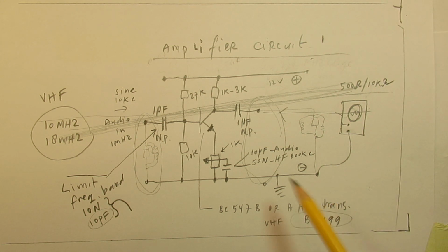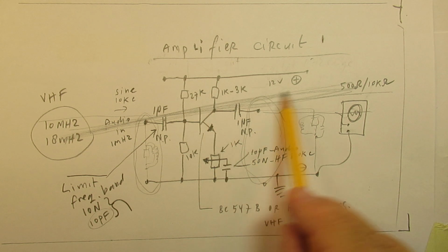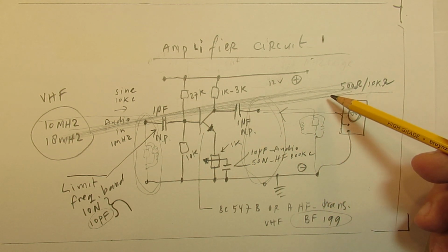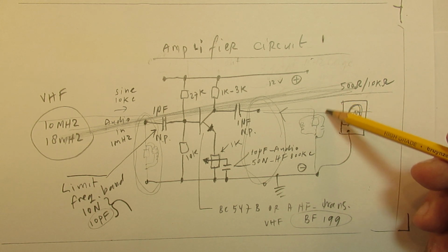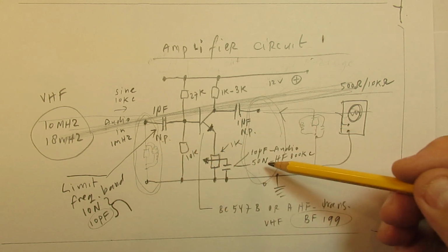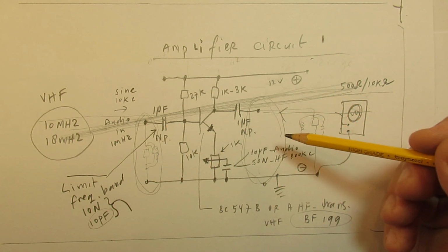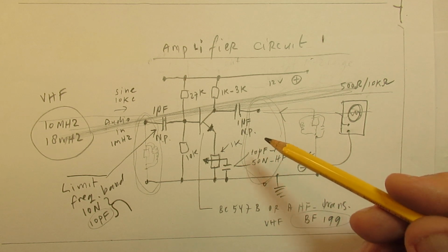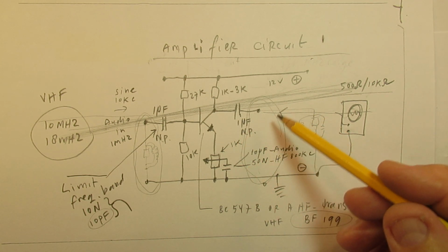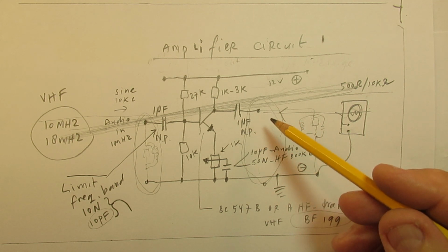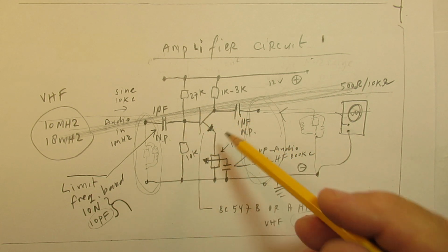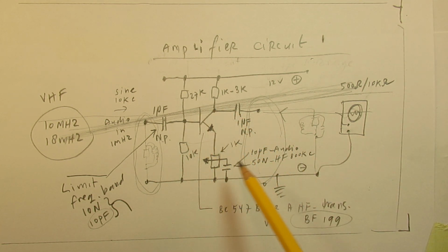And the reason is that the noise level must be kept to a substantial low level. Noise, when the impedance here or here is very, very high, such a circuit is very vulnerable for external influences. That could be electromagnetic influences, electrostatic influences, etc., etc. And especially when, for instance, here is a field effect transistor.